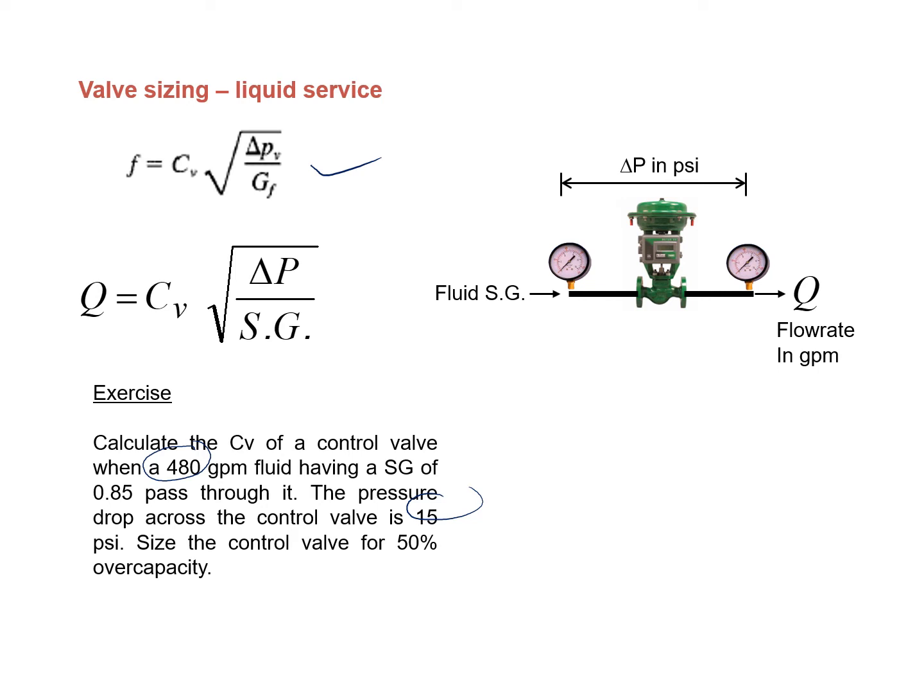If you look inside your lab, you can see that before the valve and after the valve there is an indicator. For example, this one is a flow indicator, which is to read the flow rate, and sometimes we have a pressure gauge. For the pressure gauge, we want to read the pressure at the inlet and the outlet of the valve. So we need to calculate the CV.